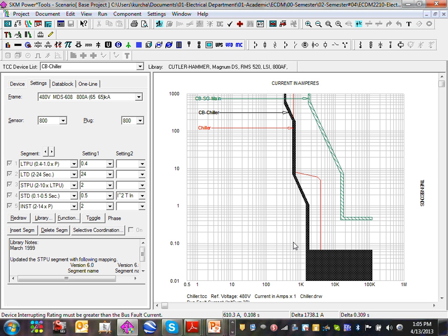Don't just grab a screwdriver, because you need to do some calculation before you start messing around and adjusting these dials on the face of a circuit breaker. Be very careful, because there's overcurrent protection coordination happening between the upstream and downstream of that circuit breaker. Otherwise, you can alter the coordination and make the circuit breaker trip faster than it should, or slower than it should. If it's faster than it should, that's nuisance tripping. If it's slower than it should, you create a fire.